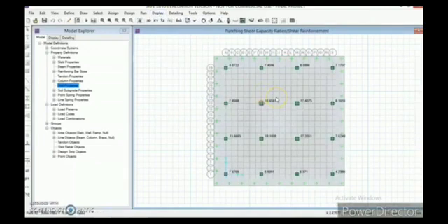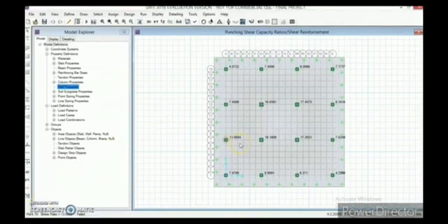So here the punching shear design values are really high. Actually the punching shear design values need to be less than 1, but here the punching shear values are greater than 1. It means that this is causing a failure of the foundation. So we need to change the thickness value. So now let us modify this, because as the punching values are greater than 1, it is a failure.